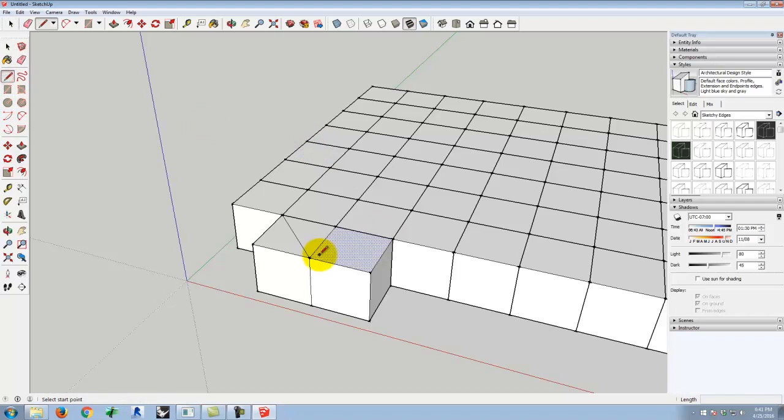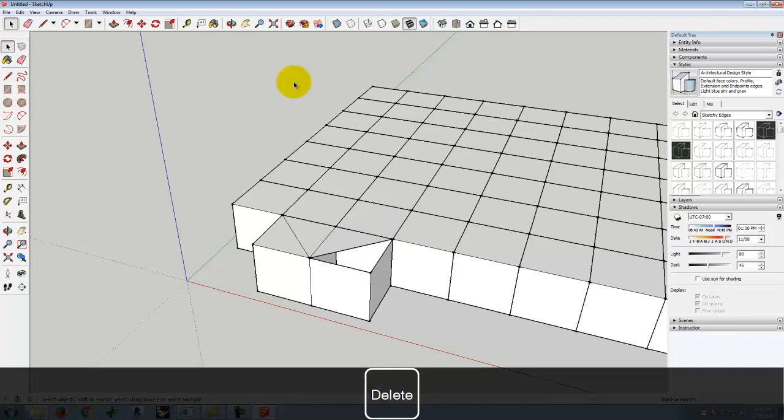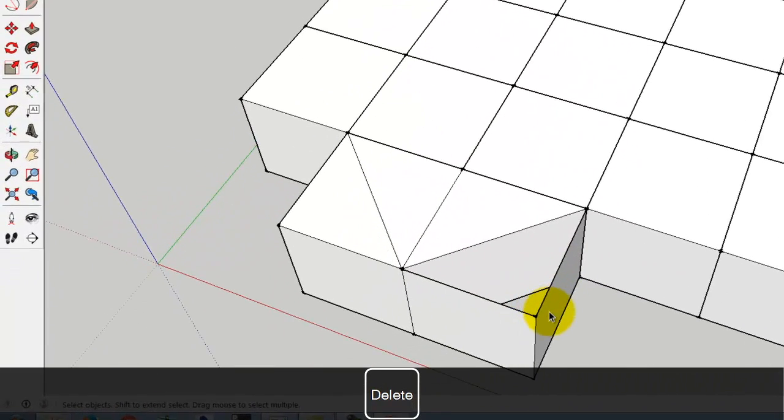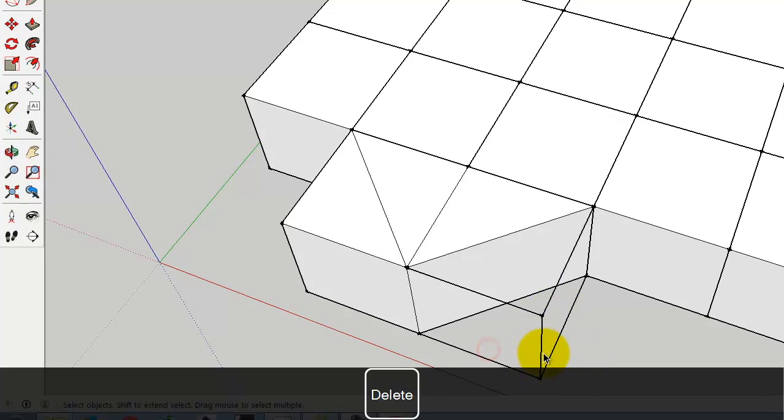So I'll go ahead and draw that line back. And then I can select this half of the surface and press the delete key. And so now I have part of this, but I don't have the lower part. So again, I have to use the line tool. And I will draw from here to there. And it fills in because I now have a completely contained object with a surface. And it also divides the lower surface into 2 halves. And I can go through and I can delete more of these objects as well, like that.